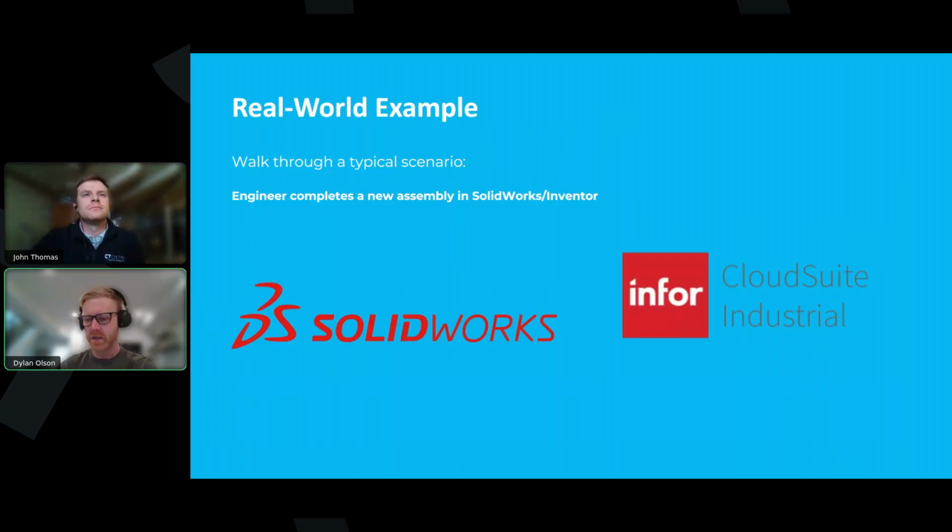But you know, you have your tree of your assembly file or part file. You can have multiple configurations, so you'll finish that design, whether it's a configured part or not. When you load it through CADTALK, you'll be logged into Sightline or CSI, and if you have multiple configurations, you'll be prompted to select which configuration you want to load. You can load multiple ones at a time if they are going to be creating different SKUs and BOMs inside of CSI.